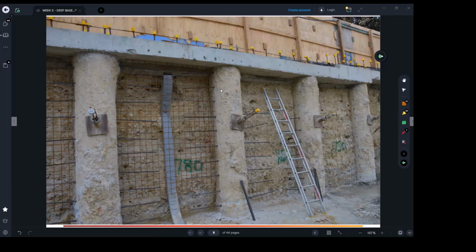They're gonna put epoxy. There are like 2 main brand names available in the market. They're gonna put epoxy, then push the bar inside for those 250 to 300 millimeters. Then they just need to wait for several hours and they're ready. They do this every, say, 300, up to the engineer.